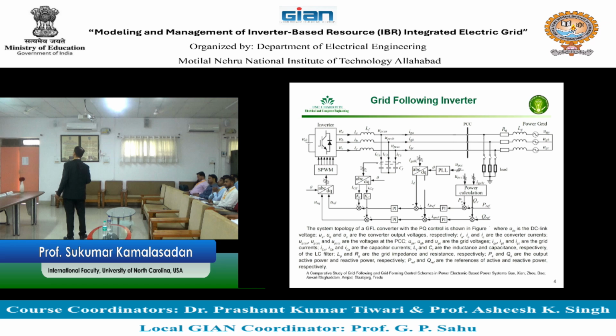Normally, inverters which are connected to and working with the electric grid are three-phase inverters. Because they are three-phase inverters, they generate three waveforms as output, and those waveforms are voltage waveforms. So the inverters that we are working on are generally called voltage source inverters, meaning at the source side, the inverter works as a voltage source inverter.